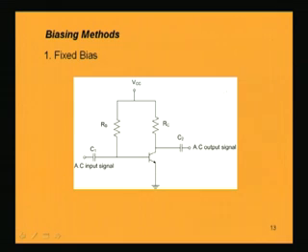This circuit is just the circuit of the amplifier, and mind it, here we are applying an AC signal and we will be getting the output AC signal at the collector. These capacitors are known as coupling capacitors, to couple the AC signal to the transistor. What role these coupling capacitors play we will see later, but before that we will concentrate on the DC equivalent circuit for this amplifier.